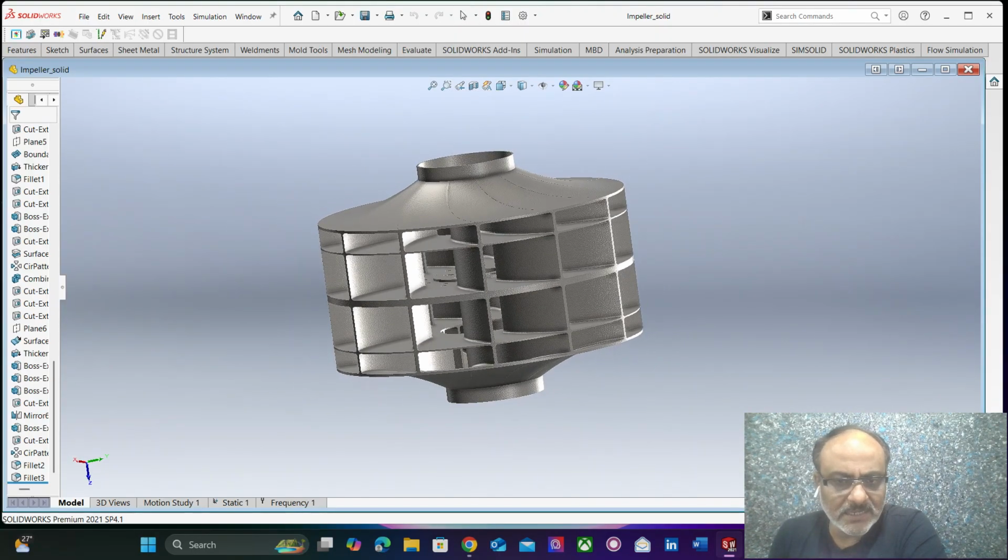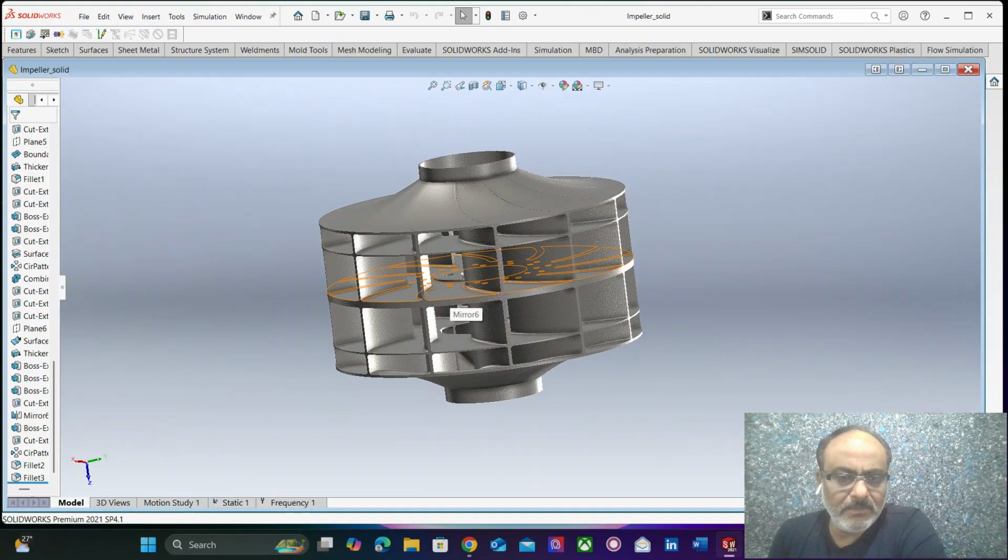So what we had done is, the main disc thickness was reduced, and the thickness that we reduced from the main disc was equally distributed onto the top and the bottom stiffeners. This means that the actual vertical blade was stiffened on either side of the central disc. So this reduced the bending stresses which acted on the blades.